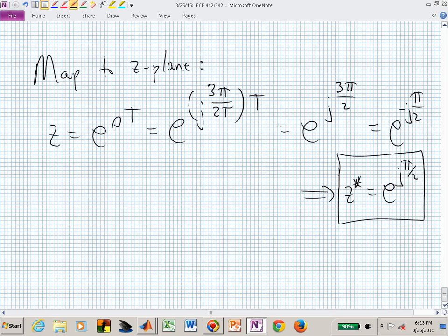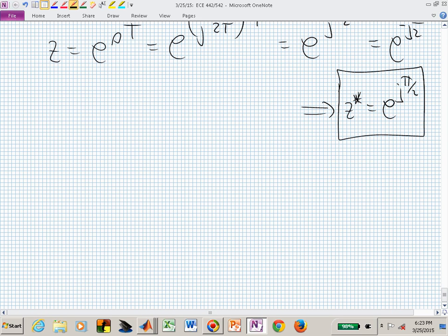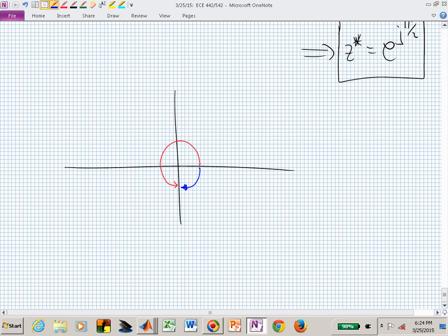What we've seen then is, by sampling at omega sub s and trying to sample a signal that's moving faster than omega sub s over 2, we now have mapped that around to that particular point, or this particular location, depending on how we wanted to write that.